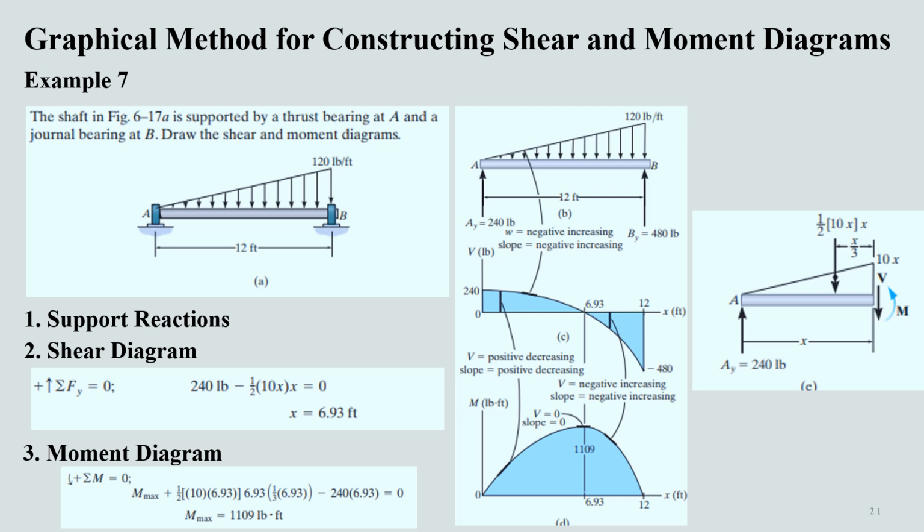That was the example of this lecture. I hope you have grasped all the concepts of this lecture. Let's delve into our last example before ending. Here we are having a simply supported beam that is being subjected to a uniformly varying load. Again, the process is very simple. You have to first determine the support reactions using summation of forces and summation of moments.